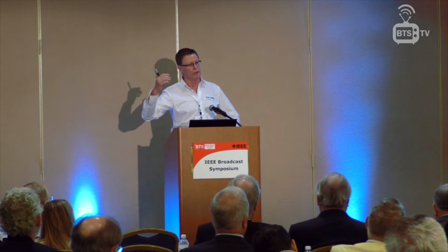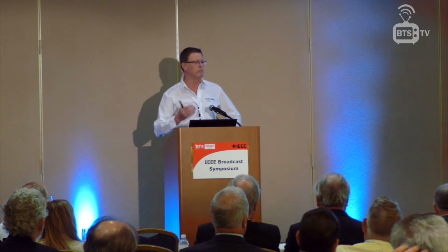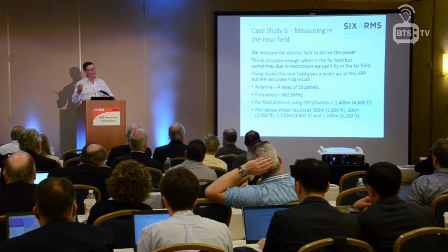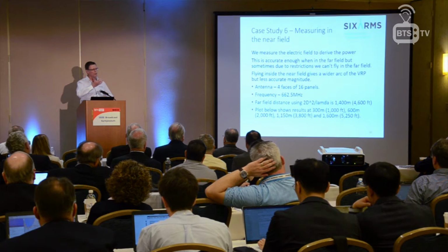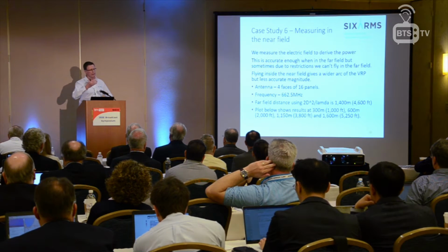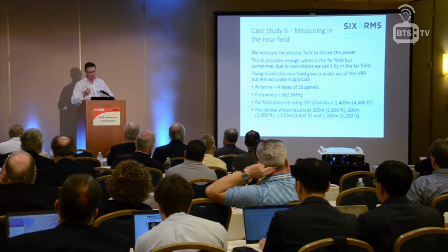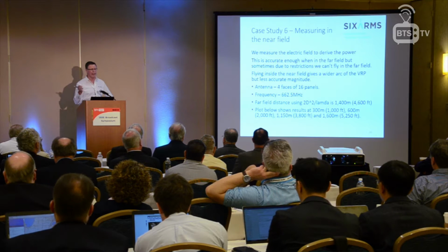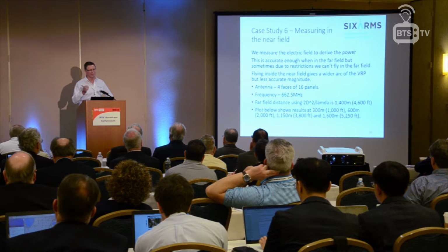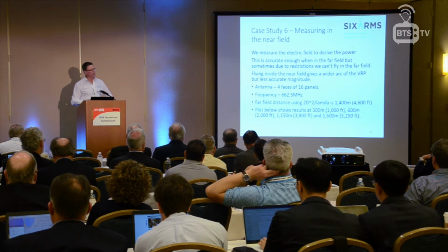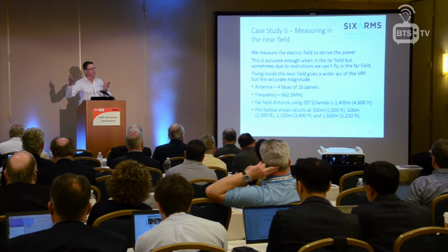that direction. So in the far field, if you only measure the electric field, you can derive the power, and that's relatively accurate. Once you get inside the near field, then measuring just the electric field won't give you what the actual power is accurately. So we decided to try and see, in the real world, what the difference was. In this case, we did several different distances from the tower.